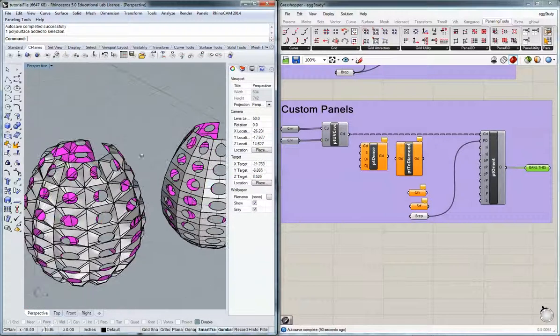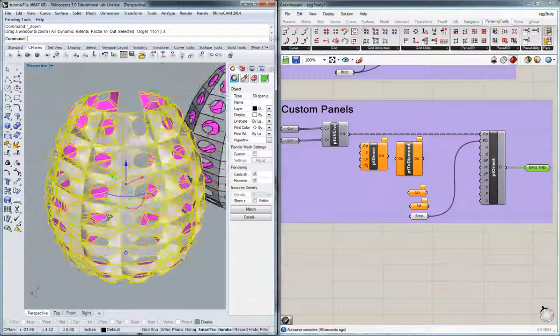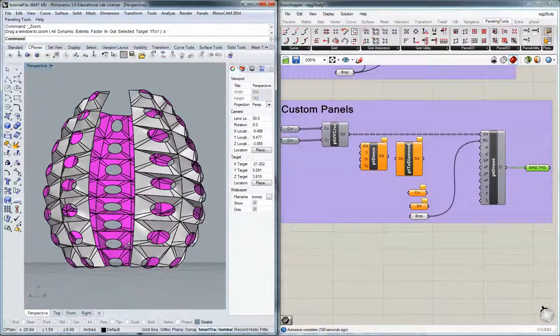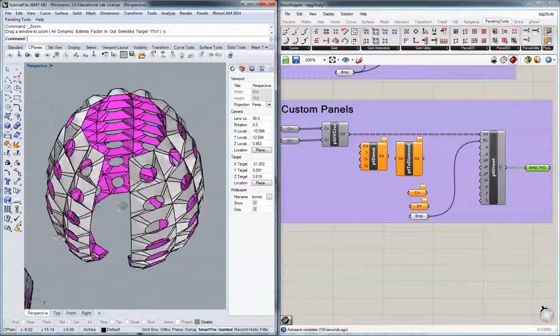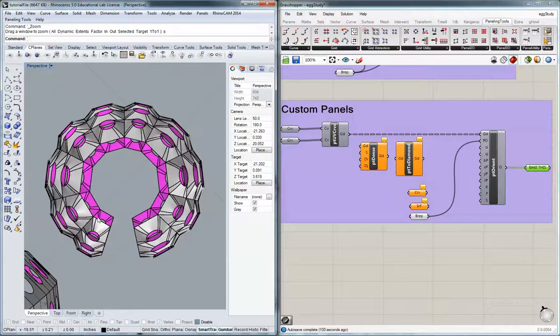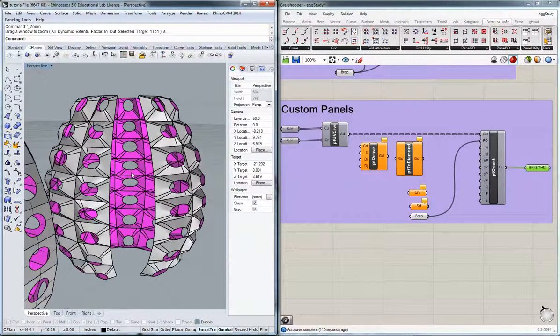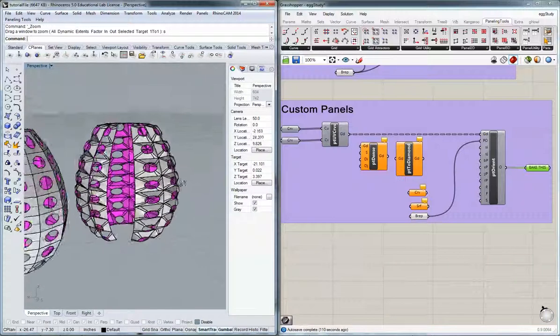You'll notice with any of these, if we spin to the back, that it's not complete. My advice would be, when you're pulling out the ISO curves, make sure that they're regular. So you could just take one of these modules and copy it around to the empty location, join it, and you'd be ready to go.